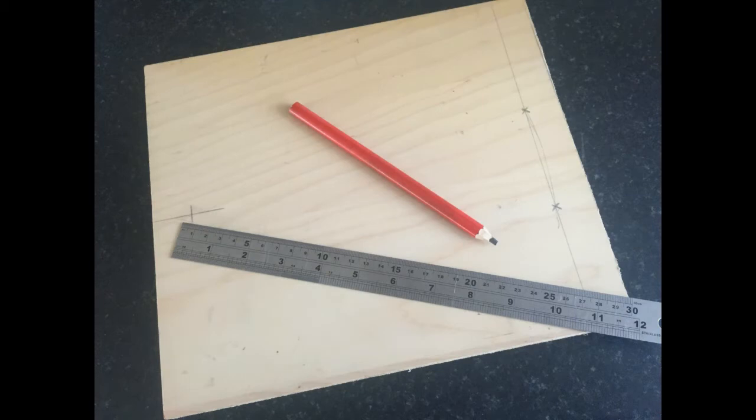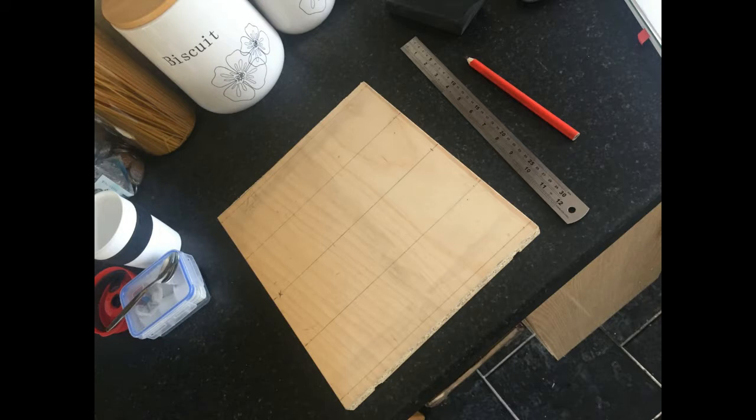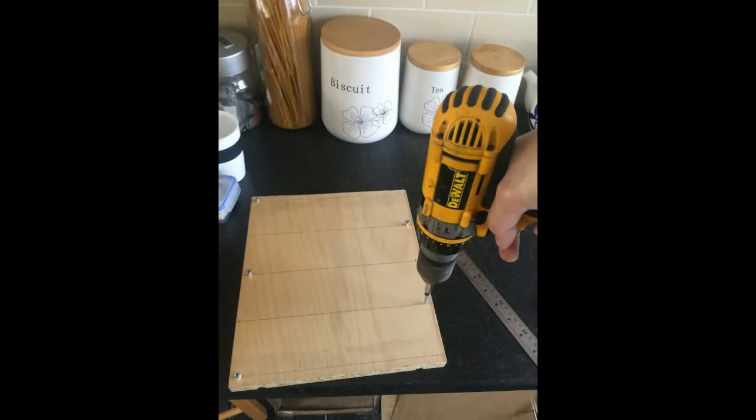Meanwhile, the sample wire was marked and sanded at 25 cm intervals to ensure good conductivity between conductors. This was necessary due to the wire being coated with insulation. The wire was then connected using wood screws as pegging points. The apparatus was then labelled appropriately.